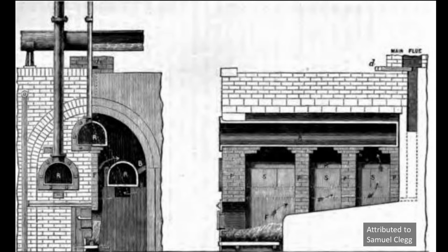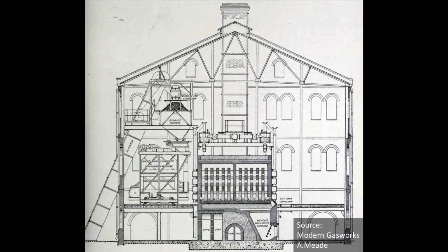Various other chemicals are released when coal is heated, including ammonia, tars and sulfur, all of which are captured and used for various industrial purposes. The arrangement for the sealed chamber varies considerably depending on the size of plant and the availability of technology at the time. Broadly, they are either horizontal or near horizontal sealed tubes in which batches of coal are heated, as in this example. This gives the characteristic rectangular cross-section to the building, with space either side for coal loading and coke unloading machinery.